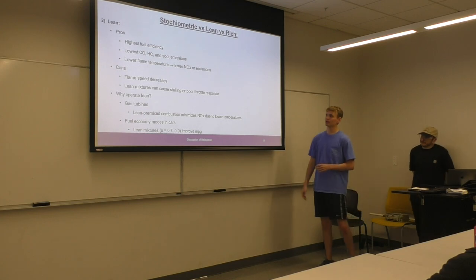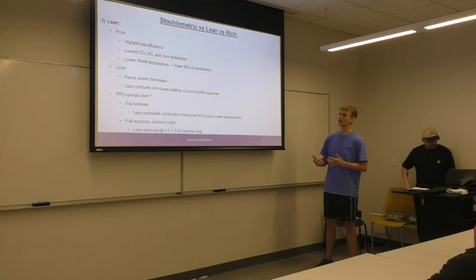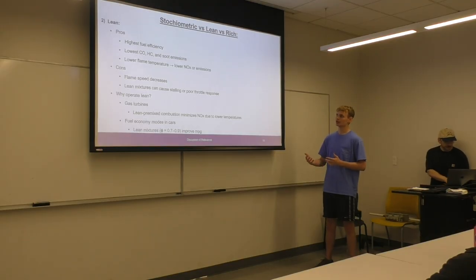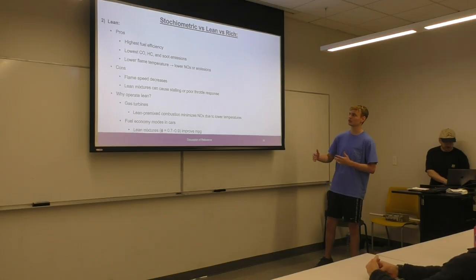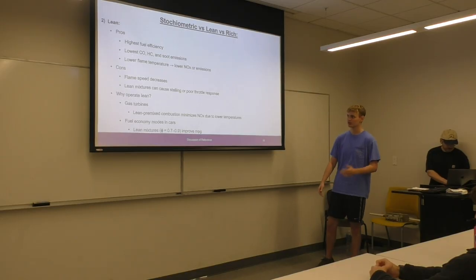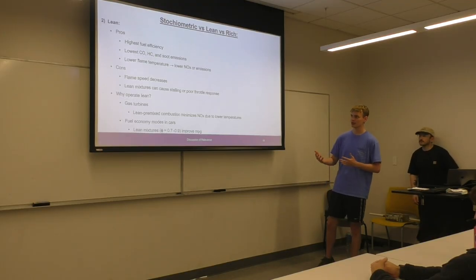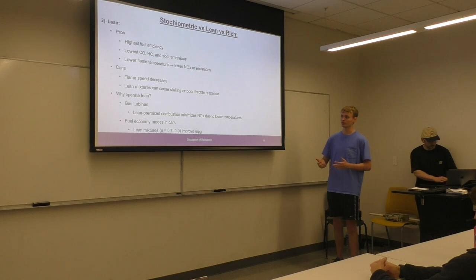So when you're burning lean, the pros are it produces the highest fuel efficiency and the lowest amount of carbon monoxide, HC, and soot emissions. Since it is a lower flame temperature, it will produce lower NOx emissions. The cons are that the flame speed decreases. Lean mixtures can cause stalling or poor throttle response in IC engines. We typically want to operate lean for gas turbines, where lean premix combustion minimizes NOx. And for fuel economy in cars, lean mixtures improve miles per gallon.